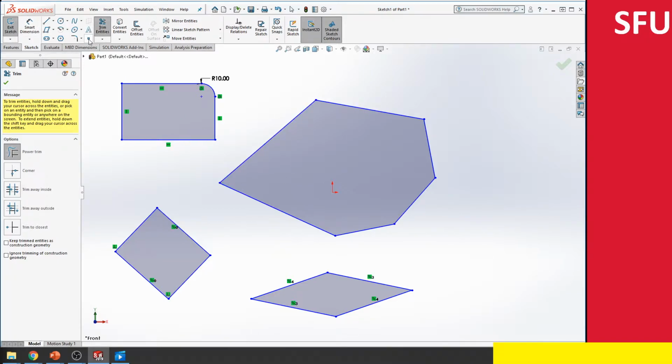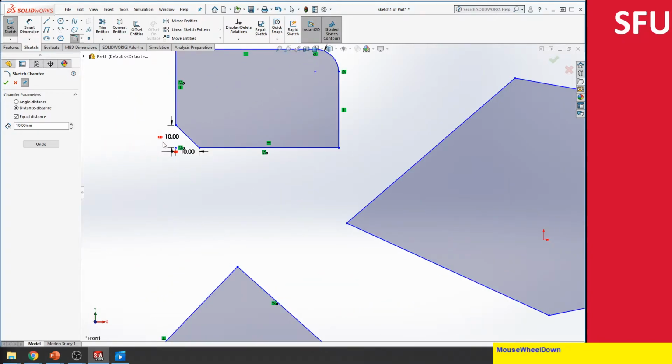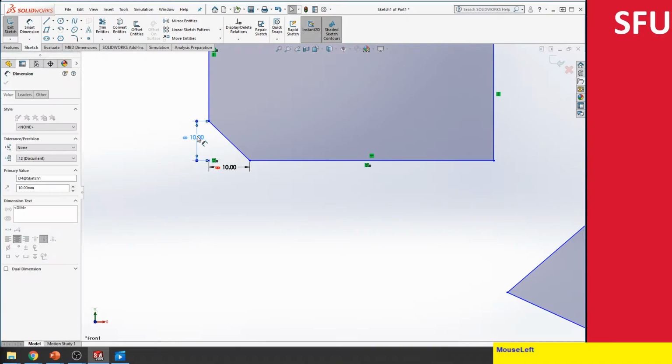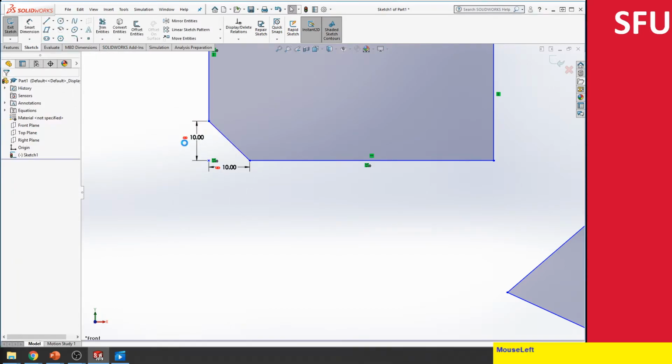We already looked at creating fillets. There's another option which is known as chamfer, which is like creating flat edges. Let's do a chamfer at the other edge. Now it does a 10 millimeter. If you zoom in over here, this is the chamfer. If I double click, I can actually change the values. Right now it's 10, and then I say OK, and that's what it's done.